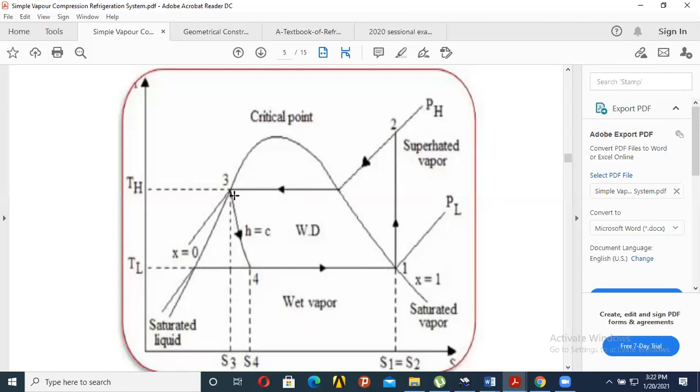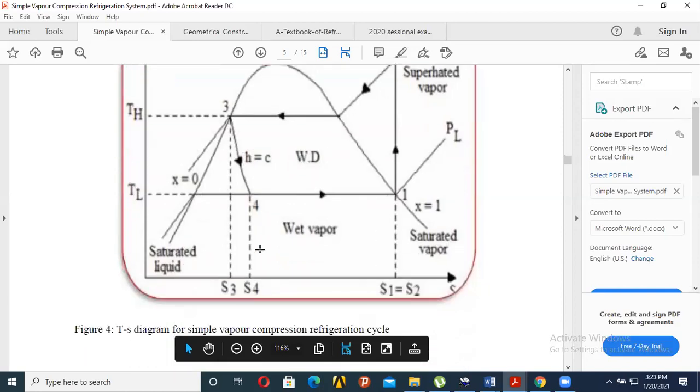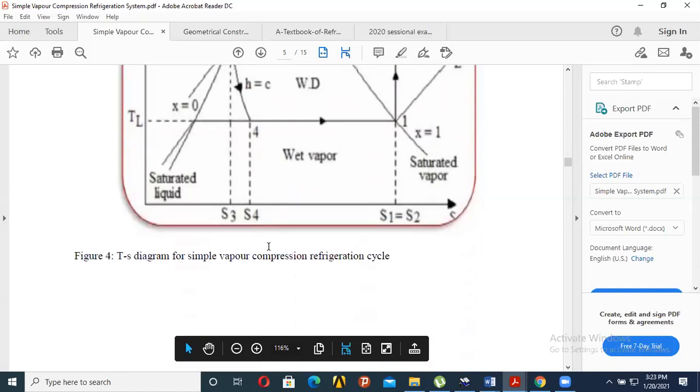because the resistance as a result of length is very small. That's why when you look at the fridge at the back, there is what we call a capillary tube. It may look small to your eyes, but when you stretch it, it's very long. Because of that length and very thin diameter, the liquid is constricted, and because of the resistance, it loses temperature and pressure. Then the liquid comes back cooled, and it's able to pick up more heat from the fridge or any space, and the cycle repeats itself. So this is how this cycle works.